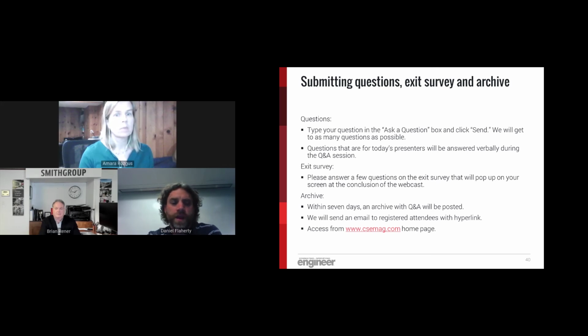Thanks, Mara. Some of the advantages of natural gas gensets, like I kind of went over before, are that you don't need to plan for having storage on site with natural gas gensets, and there's more opportunity to do load shedding with utilities than with diesel gensets. However, they're physically larger machines because they require a larger footprint to put out a similar amount of power. Diesel gensets are more compact, and while you have to store their fuel on site, you always know that you have that fuel on site, and you know that that service can't be interrupted in the event of an emergency.